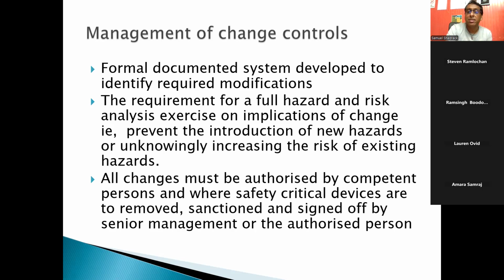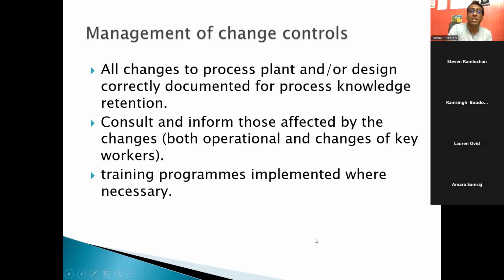So if you modify something, follow the MOC form. If something changed with a hazard, follow the MOC form. All changes must be authorized by competent persons, and of course, it must be captured. So all changes to the process plan. Anything that wasn't a normal replacement, like a normal inspection, or the end of the life of the product anyway, that doesn't need a MOC form.